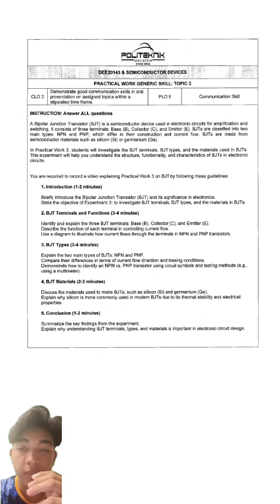Conclusion. Through this experiment, we gain a clear understanding of how the bipolar junction transistor (BJT) functions, starting with the roles of its terminals: the base, collector and emitter. We observe how a small current applied at the base is able to control a much larger current flowing between the collector and emitter, which is the key operating principle of BJT. This makes them highly useful in both amplification and switching applications.